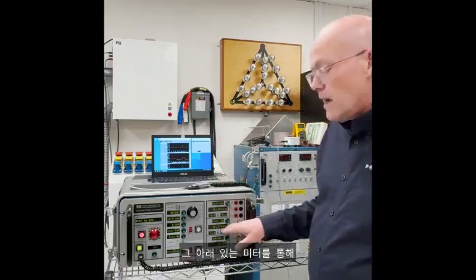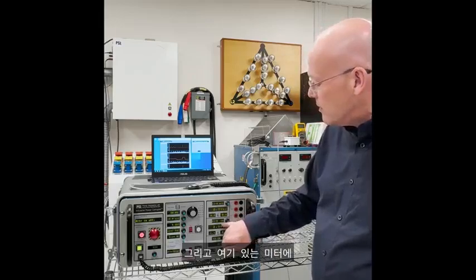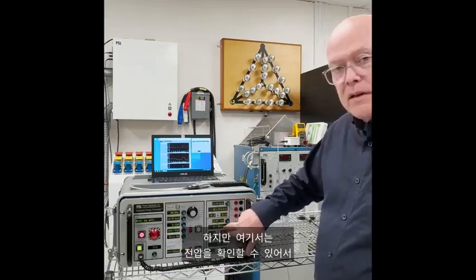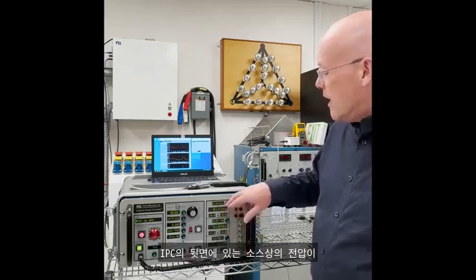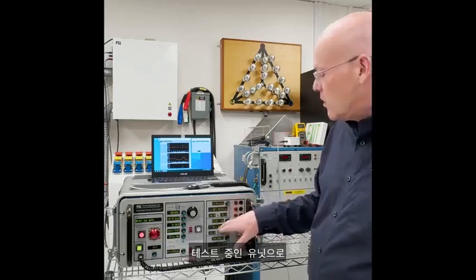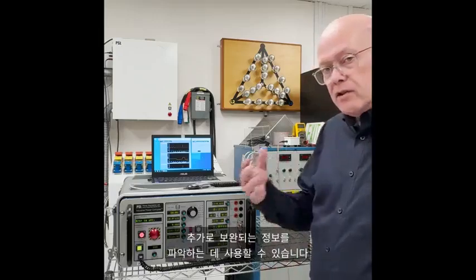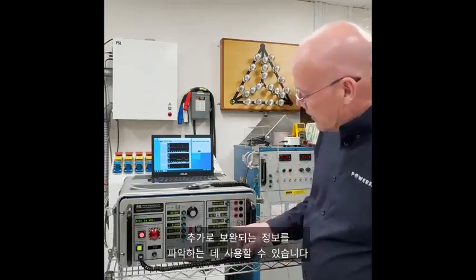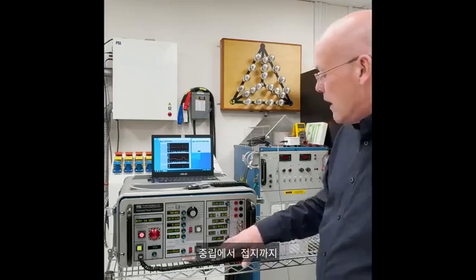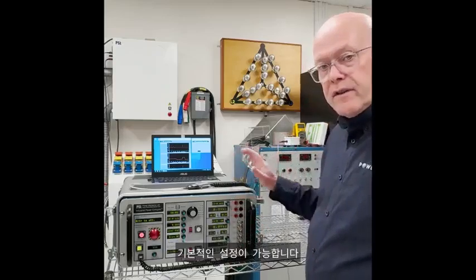For the next set of meters, we have line 1 to neutral, but on the load side, and you can see indicated on the meter here, it says load, and again, there's reset capability for min and max, but it will give you your voltage so that you can see very clearly what voltage you have on the source side at the back of the IPC and what you have on the load side that's going to your unit under test. And then the third meter, you can use that to supplement information. Here we have line 1 load, but equally when you set up, you could have neutral to ground. You could have a number of other parameters that gives you a full appreciation of the setup and what to expect.